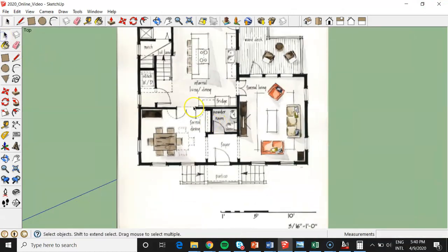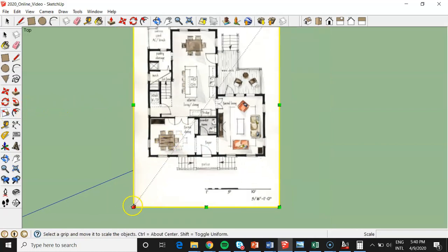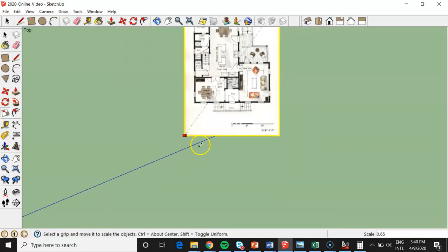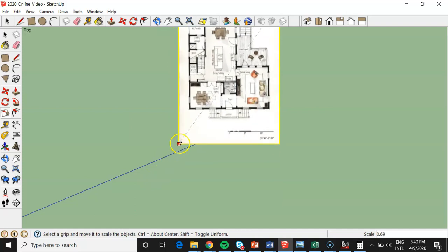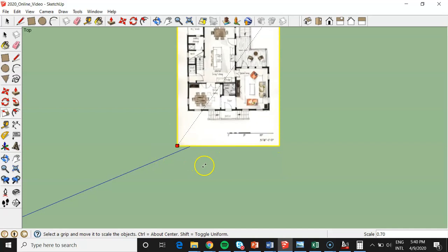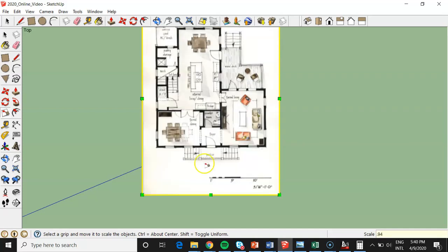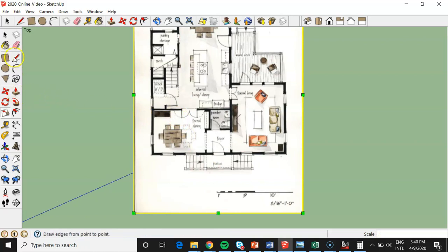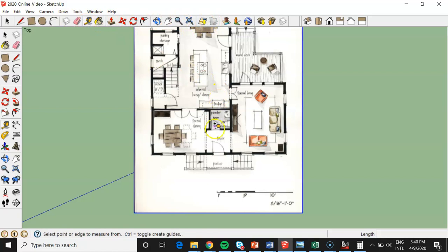So select the image, select the scale, start the pull. Now I'm not holding down on the mouse. Once I clicked on that node, it locked it in. And now you see the scale factor at the bottom right, 0.94, enter. And that should have shrunk my image quickly and not too much, so we might not have noticed it.